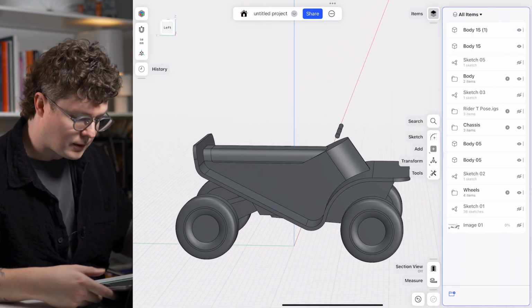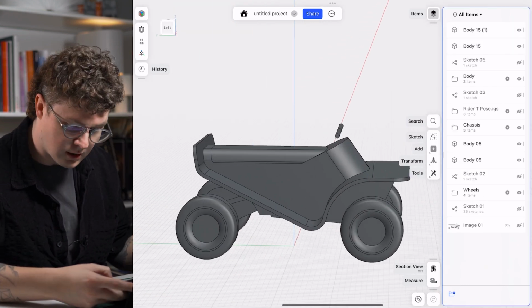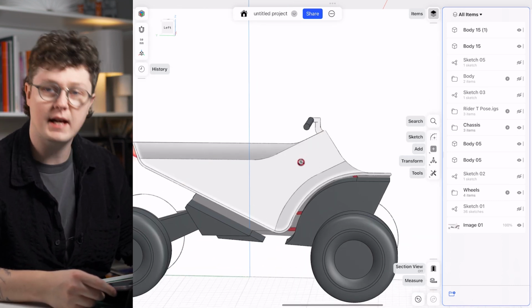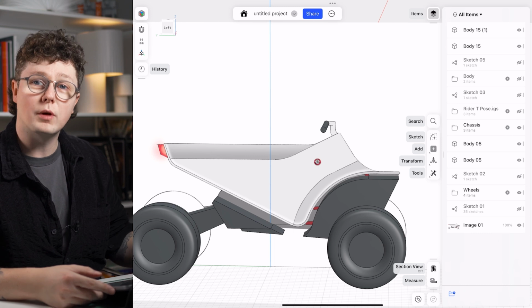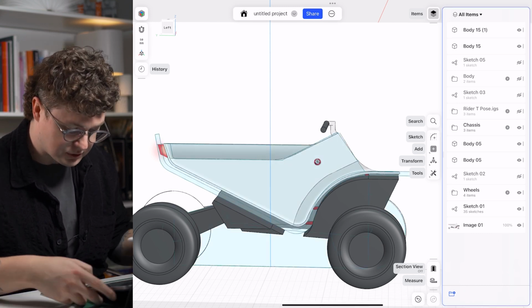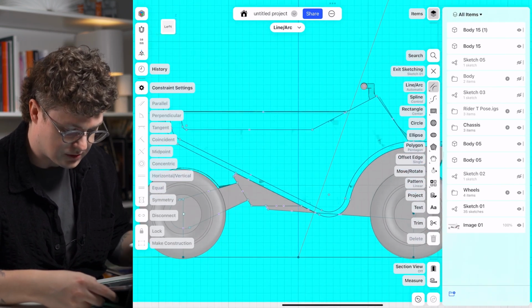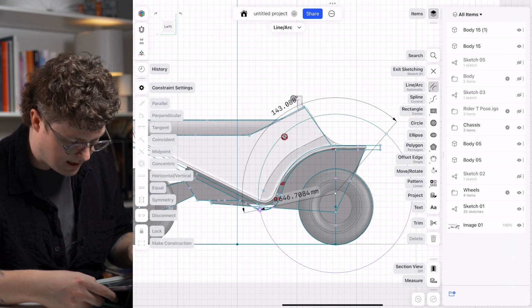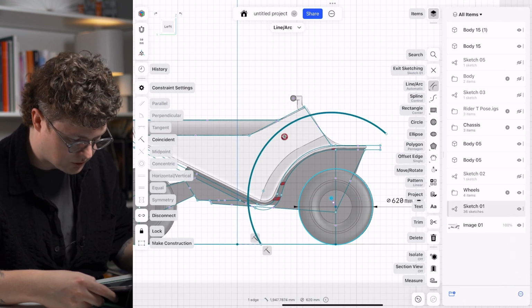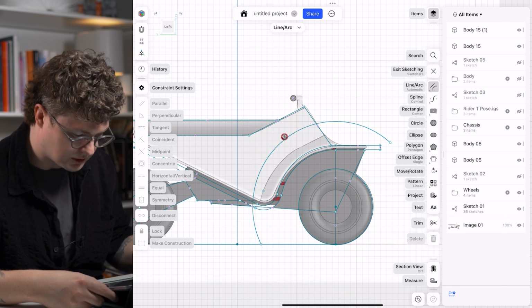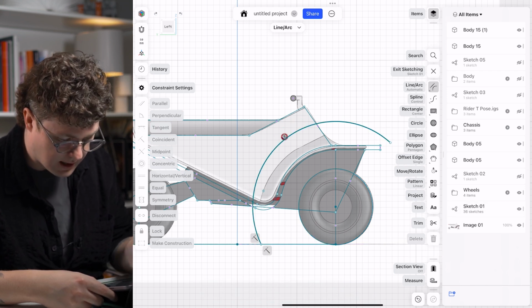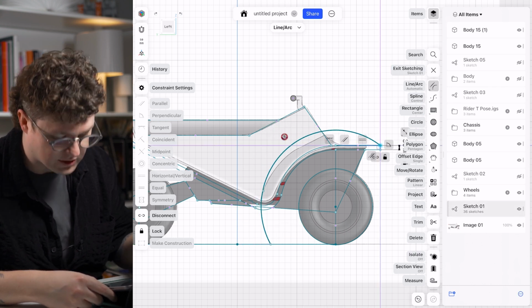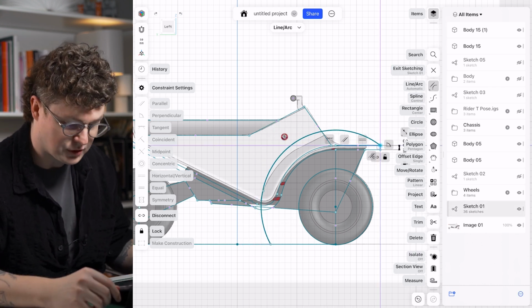And the other thing that I want to do is, you'll notice on the sketch is that I had this cutout here of the main body. And what I can do for that is to come into the original sketch and I can just double tap to start editing. And what I want to do is draw an arc that basically is concentric to our front wheel. So everything is nice and concentric. And I want to make a solid body out of this eventually. And that will be a solid body that we can sort of throw away, right?